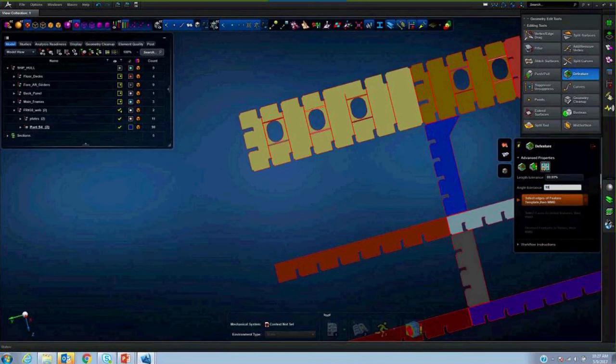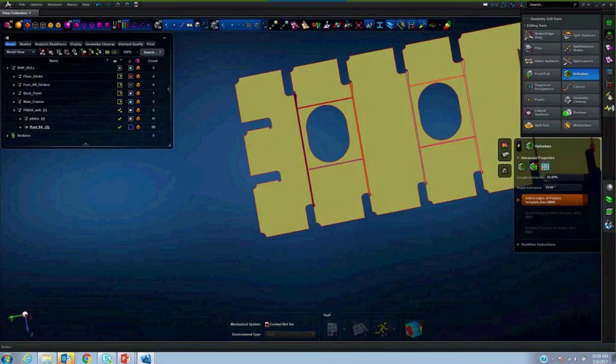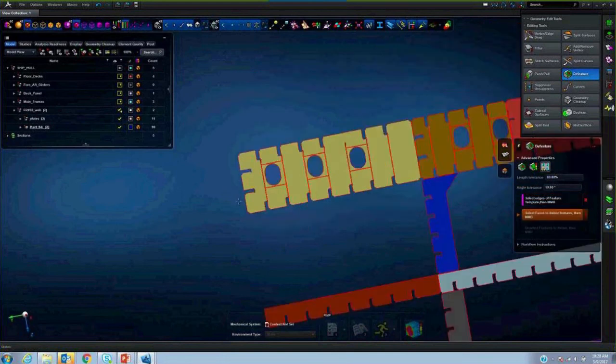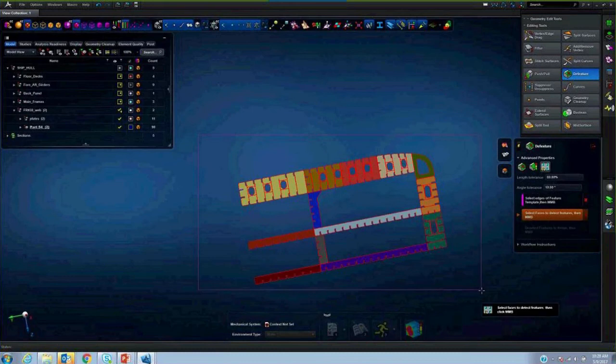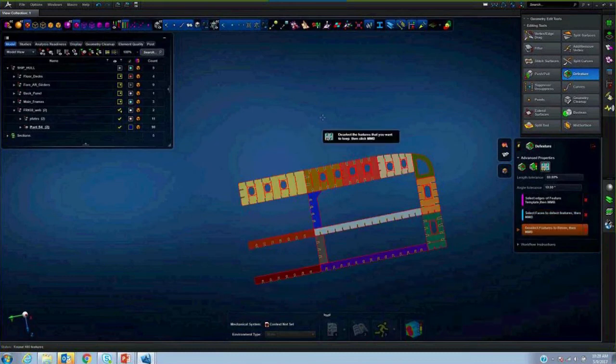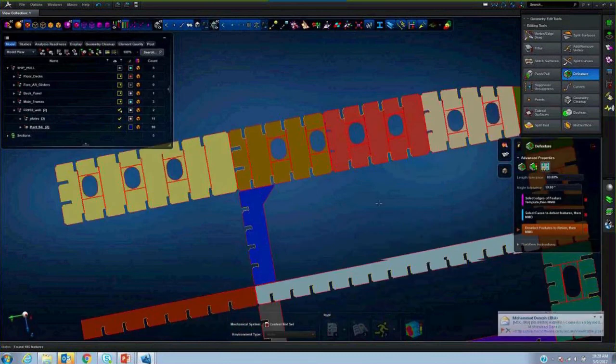And maybe I'm just introducing about 80% of the length tolerance and 10 degrees with respect to the angle tolerance. That means within that variation, once we identify one of them, we'll try to search all those similar patterns in the model. Let's say, and now I'm going to select one of this pattern here, keyhole. All right, and then I'm going to select in the entire model how many of such things are there. And it found 106 such features of keyholes in this model.